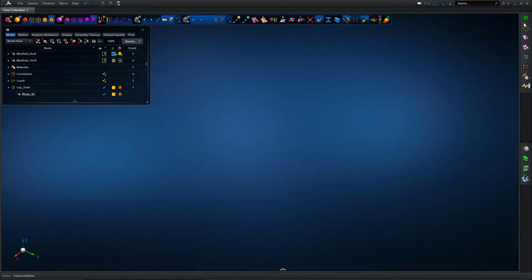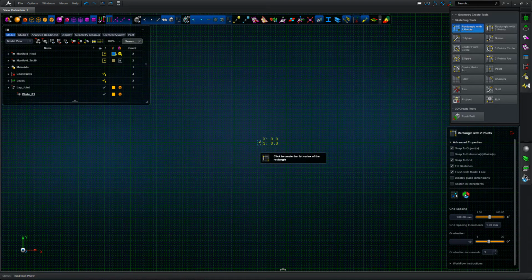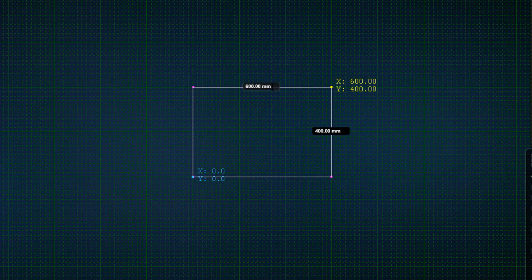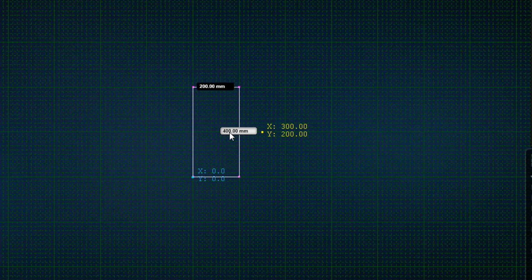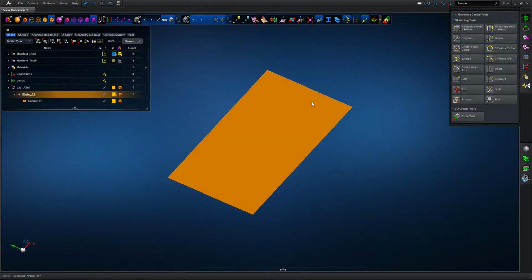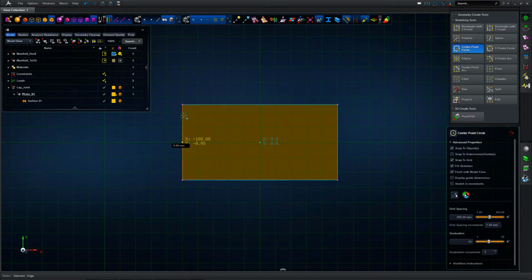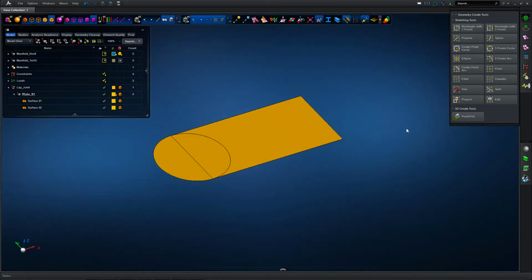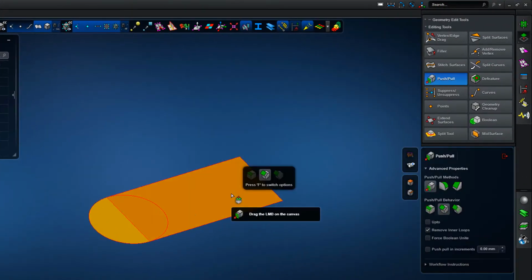Okay, so in this example we're going to look at some 3D modelling and analysis with hexahedral or hex elements. For the first exercise we're going to build some geometry directly within Apex, so this hasn't been brought in from CAD, so we're looking at some of the sketcher tools. We're developing a rectangular surface based on predefined dimensions, putting a circle on the front of the surface. Ultimately we're going to be developing a double lap shear joint using three-dimensional hex elements.